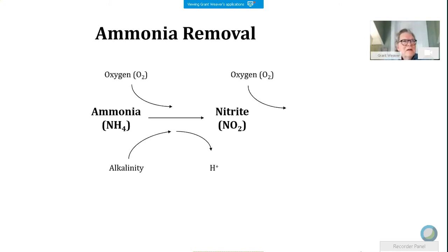So we can measure the alkalinity and it's a precursor. It's advance warning. It's like looking at your ice cubes. As they disappear, the water's going to be getting warm soon. If the alkalinity disappears, the water's going to get more acidic. It's too acidic, and this process shuts down. So we don't want that to happen. So that's step one,